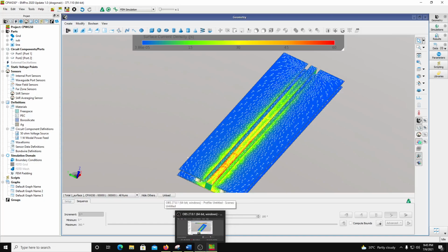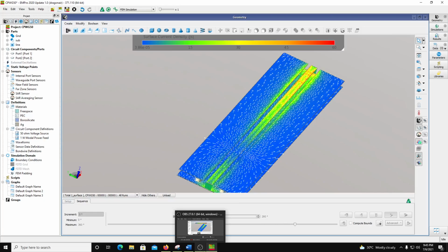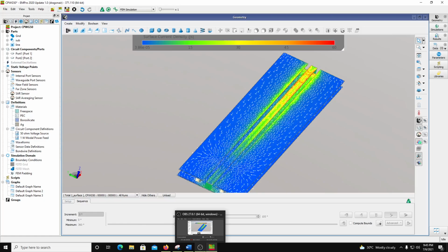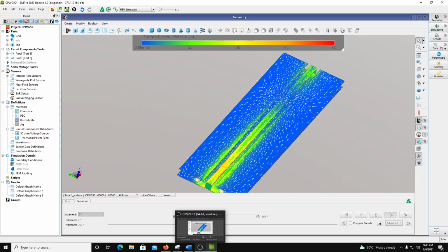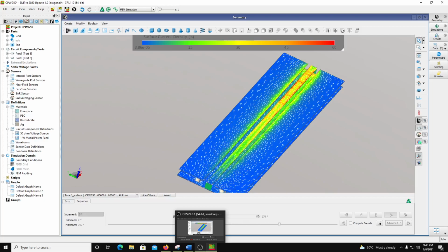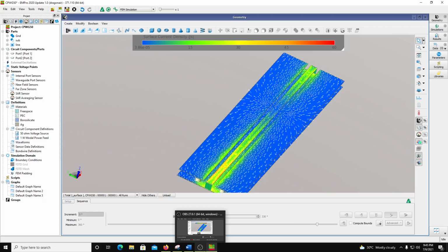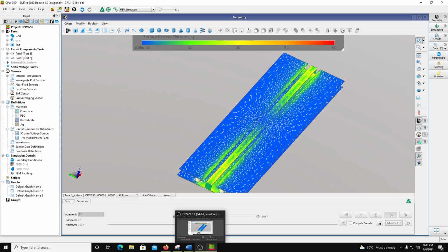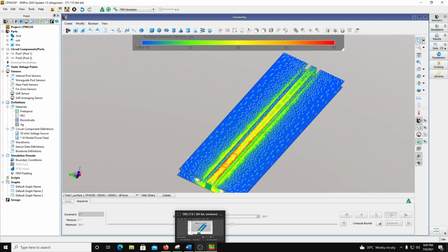We could not do a one-click button drawing or one-click button transfer of a design from the ADS to EMPro because we were drawing on metal 6 and 7, which are kind of at a height. Okay, so we had to make a correction for that. So in some later designs I'll show you corrections. There's nothing wrong with the one-click functionality which Keysight has provided. It's just that my definition and my drawing, I have to be aware of what layers I'm drawing on, right? And accordingly I might have to do some changes once I come to EMPro. Okay, had it been just the two metal layer, it would have been a one click of a button. I wouldn't need to do anything.